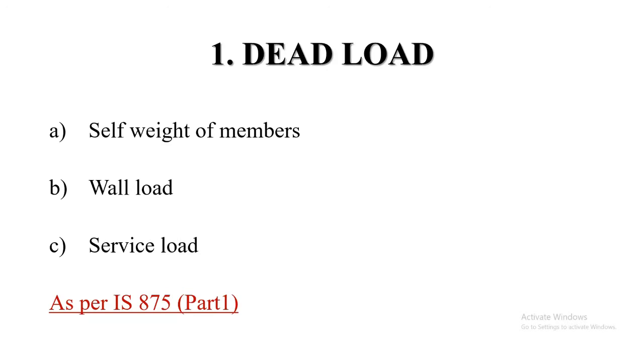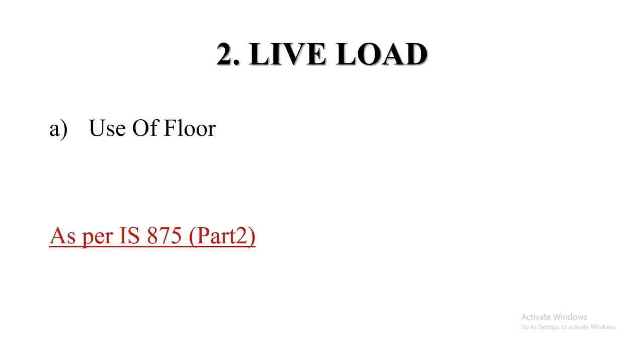And the service load. Service load depends on any kind of materials which you are using, like a particular kind of tile that has a particular service load. These things are mentioned in IS 875 part 1, if you go as per the Indian codes. And the live loads. Live loads depend on the usage of your floor. IS 875 part 2 has a particular table in which the loading has been classified as per the usage of the building, and in which condition you can take 2 kilonewton per square meter, in which condition you should take 4 kilonewton. Everything is mentioned, so we'll look into that IS code as well.